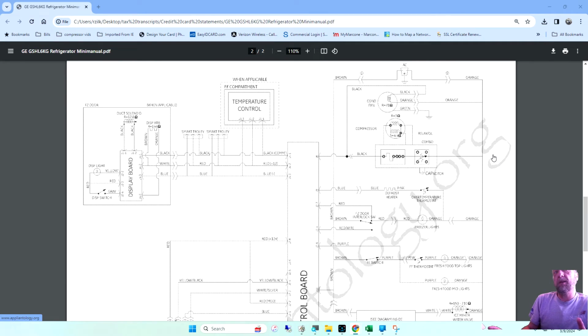Well, here's what could have happened. You were putting the cover on when it stopped, and if one of those plugs or connectors was slightly loose, and you disconnected and connected it back again for a second, the board might go into a time delay, because the connector wasn't good, so it lost voltage and the compressor stopped, and then the voltage came back on. It might have said, hey, the power was off and on for a second, and then went into a time delay. I don't know. I guess the first thing you'd want to do is check voltage to the board.